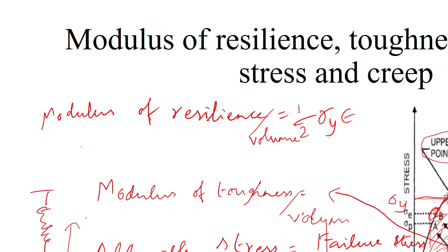And for brittle materials, I think it will be the ultimate strength divided by factor of safety. Sir, how is this factor of safety calculated? See, it is based on experience only, bro.